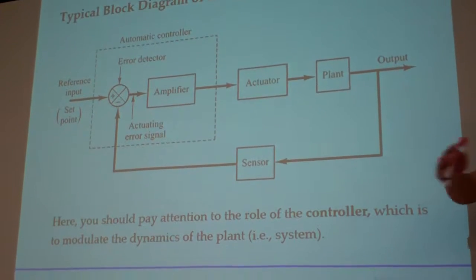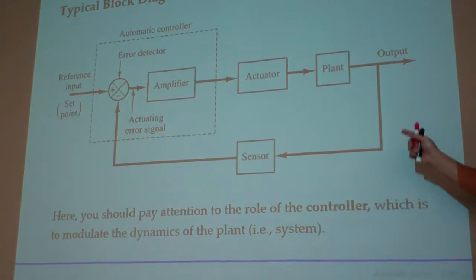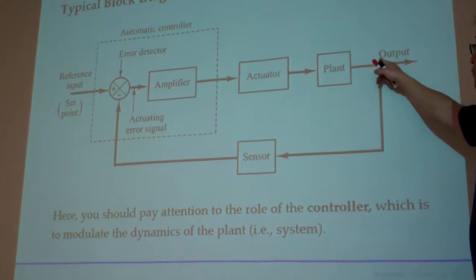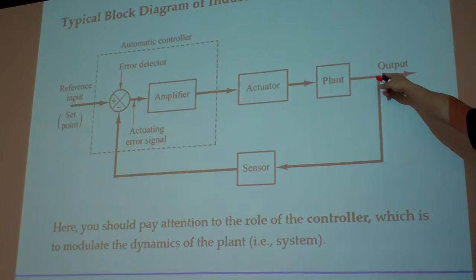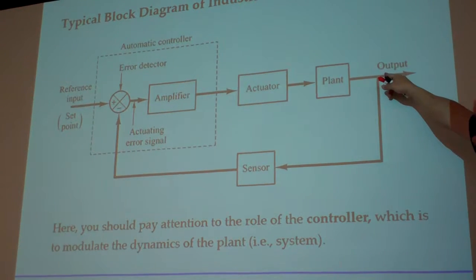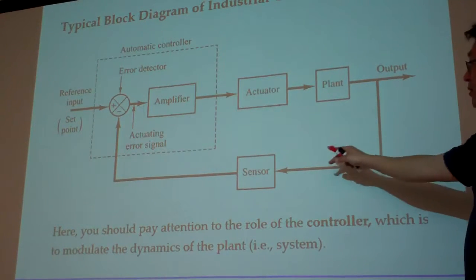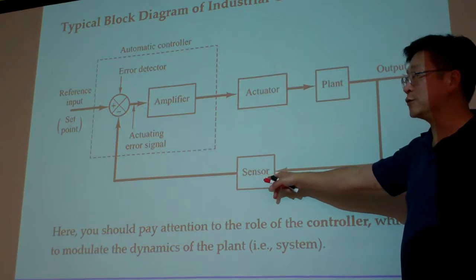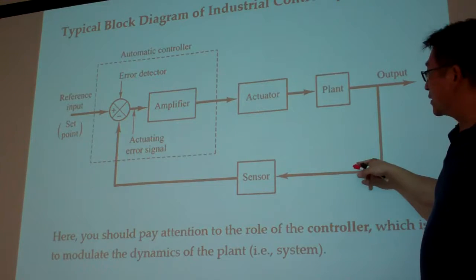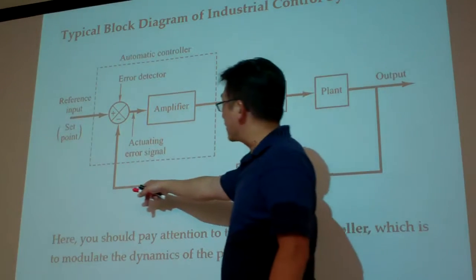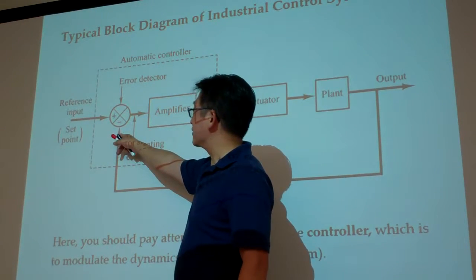So here is how much we want to sweep. We take the output. Say it only goes to 85 degrees, still with 5 degrees of discrepancy, then we put in sensors, like tachometers, taking the output, and from the sensors we know, okay, here we only have 85 degrees.